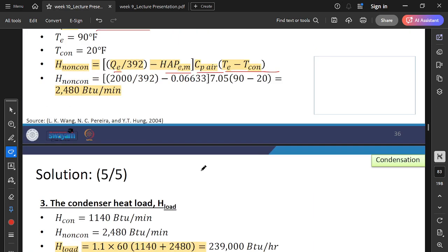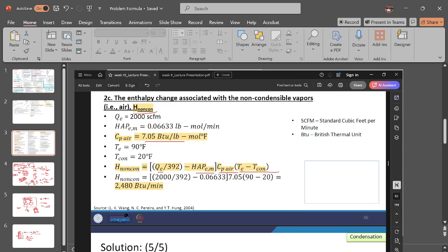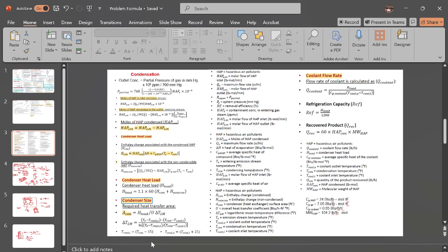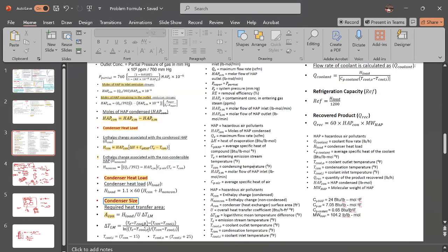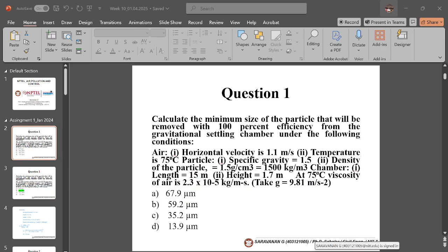Okay. So TE, T con, how to find? That formula also I have given here. T con, T cool, everything is based on this temperature only. T con minus 15. T cool O, if you want, T cool I, after finding that, add 25 degree. Everything is in Fahrenheit.